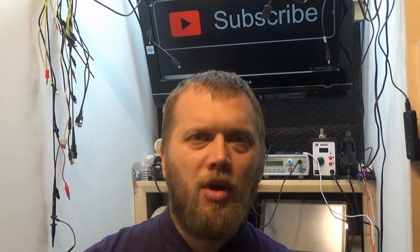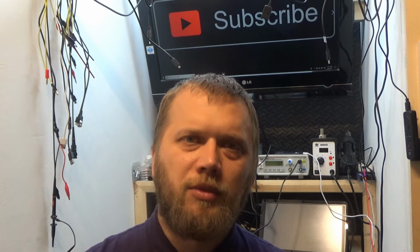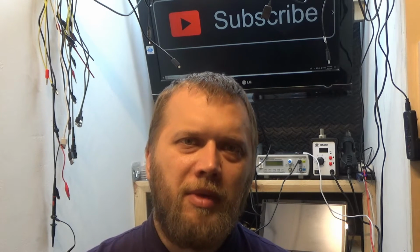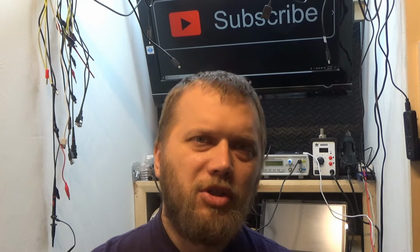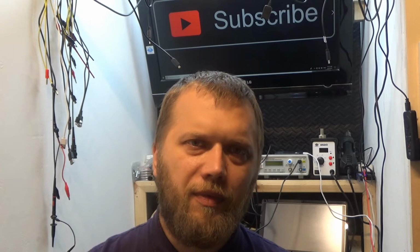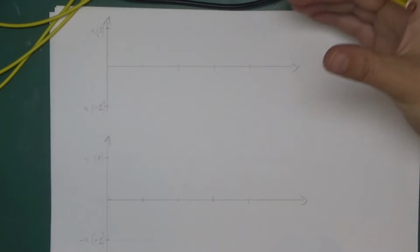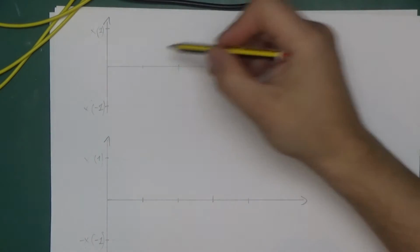It's supposed to measure the entire signal, not depending on the waveform that it's dealing with, and display the heating value, or the RMS root mean square value, on the screen. So when you're doing a measurement, you know exactly what sort of power levels you're dealing with. That's the idea of the RMS measurement. I've got two highly advanced charts prepared here. So let's start maybe with a sine wave.